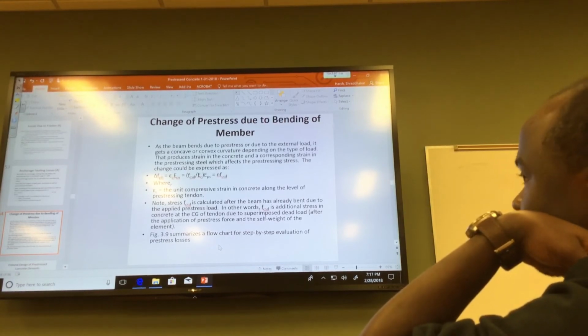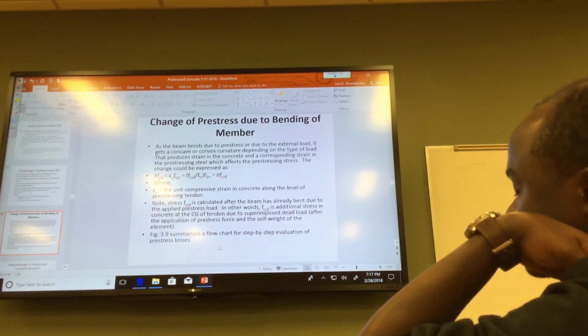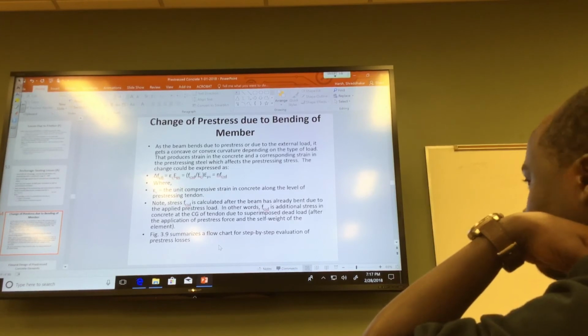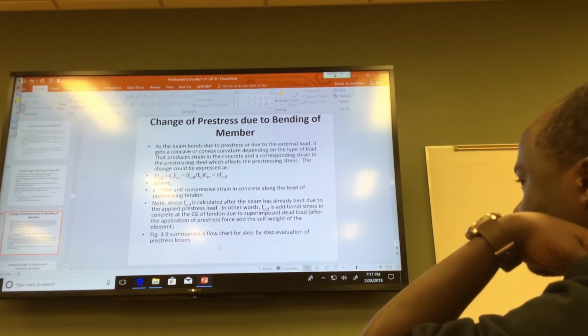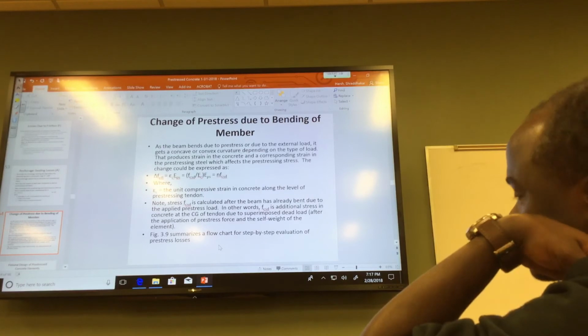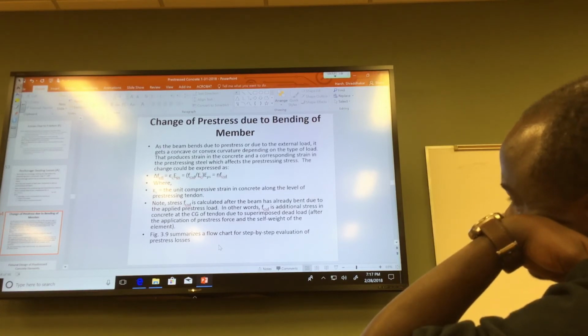This room may not be a classroom. It may be a seminar room with hardly any furniture or lighter furniture or what have you. It's changing, but it still has a minimum value. But if you know that for the next 5 years, this classroom is going to have this kind of furniture, then might as well call it sustained load and use it in your calculation for creep and relaxation.